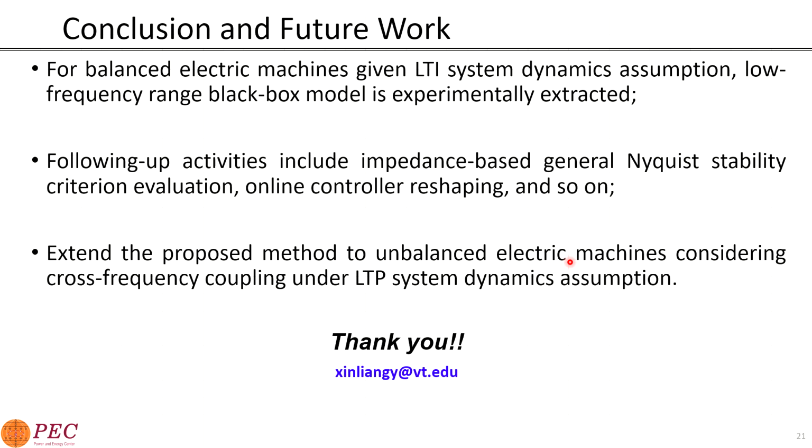The follow-up activity after the impedance extraction could be impedance-based stability evaluation using the generalized Nyquist stability criterion, or online controller reshaping, in other words, adaptive control and so on. And also, in the future, we want to extend the proposed method to unbalanced cases. So the so-called cross-frequency coupling under the linear time periodic system dynamics assumption will be considered. Thank you. This is my presentation.